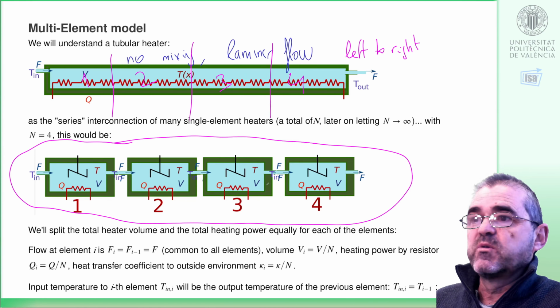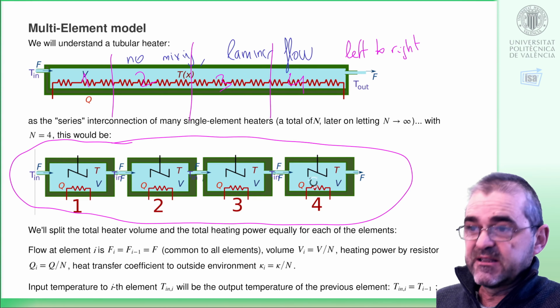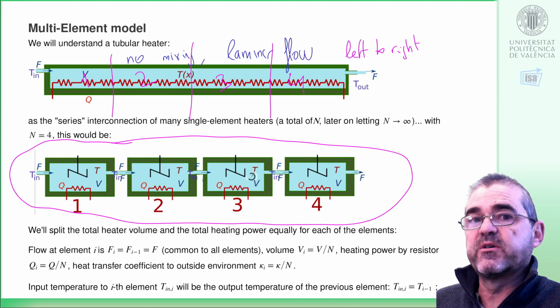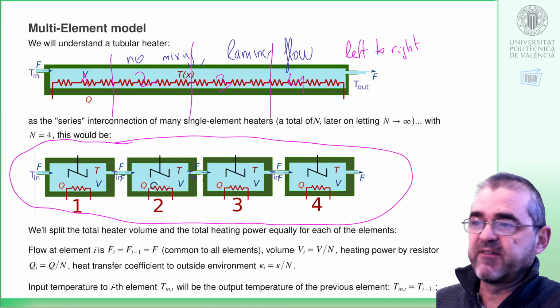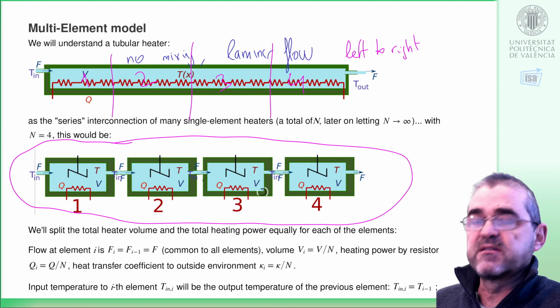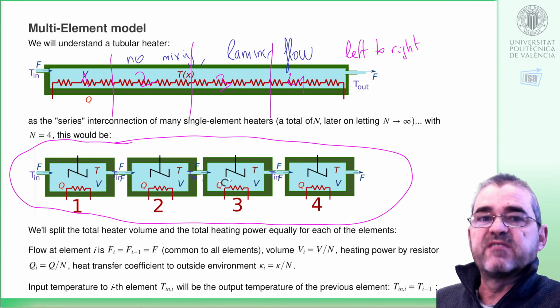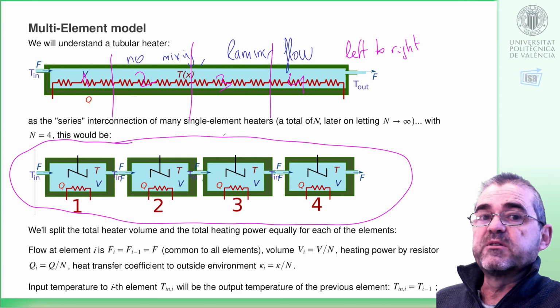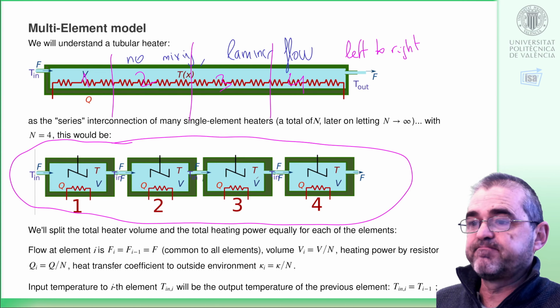In this case, we have split the heater in 4 finite elements. That's what usually needs to be done in nonlinear simulations if the equations we are going to derive later on have no analytical solution. So finite element is a key aspect of simulations of thermal phenomena, vibrations, electromagnetic waves, okay? But we are going to formally make the number of elements infinite.